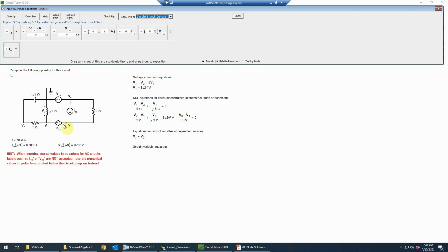First we need a term for a current source value, which will just be a fixed current, as indicated here. Again, that's a constant current source, fixed value, as the tooltip says. And then through the 8 ohm, we need a difference of node voltages because neither end is connected to ground. So we need a term like that, and those two currents will sum to I naught.